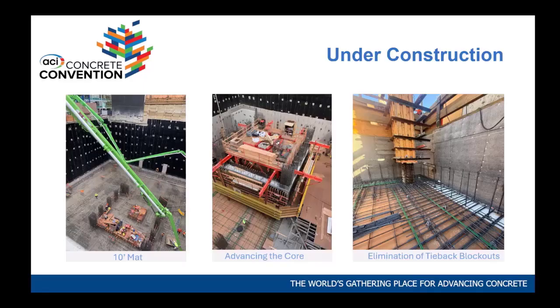We allow them to put the slabs against the shoring system. And then they detension the tiebacks on the shoring system. Now the slab becomes the bracing for the shoring system, not the tiebacks, so you don't have to do blockouts in the basement wall. And then you don't do the basement wall till later. So this is formwork put at the joint of the basement walls. You have a basement wall above, basement wall below, slab in.